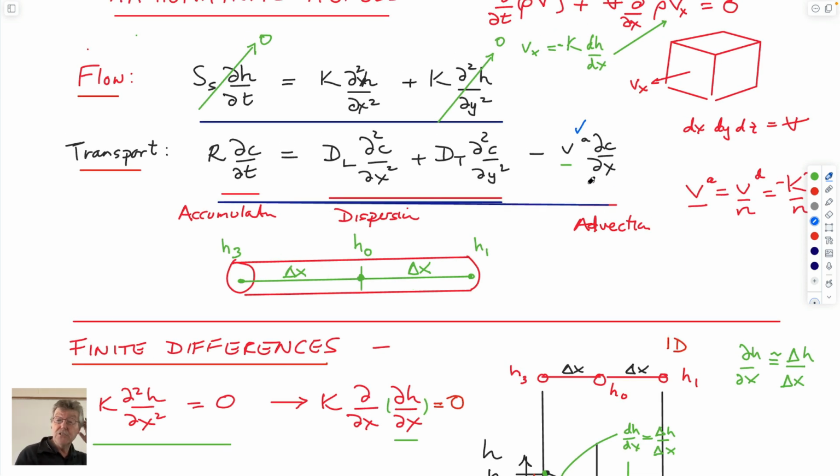It also turns out that this is quite a difficult equation to solve. Solving second order PDEs is much simpler numerically than solving first order ones, because they're unstable when you solve them numerically without doing it the way that we're going to do it today. So what we've done with this second order equation is we've described a mesh that has all these nodes in it from upstream to downstream, and we try and solve how this head is distributed on the framework of this mesh as it goes downstream.